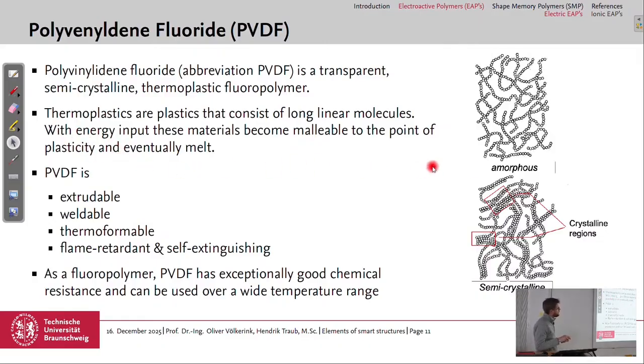So here we have the chain structure of an amorphous thermoplastic, and a semi-crystalline one is a thermoplastic which has amorphous regions, but in addition also some crystalline regions here, and these crystalline regions we need for the piezoelectric effect.